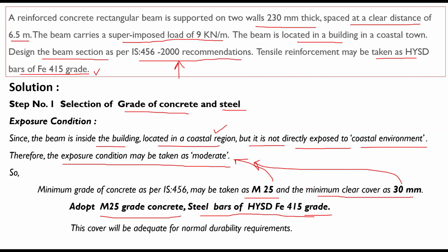So based on this information, because the grade of concrete as well as the minimum clear cover which we have decided is based on the moderate condition, and on consultation with IS 456, we can say that this 30 mm minimum cover will be sufficient or adequate for normal durability requirements.